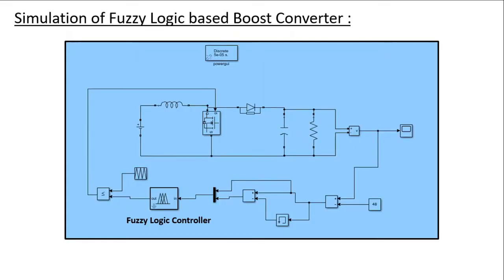This is a MATLAB model of a fuzzy logic based boost converter. If you carefully observe, we are using a fuzzy logic controller in the closed loop system. I made a couple of videos with respect to open loop simulation and design of a boost converter, and closed loop simulation of a boost converter using a PI controller. So over here I am using a fuzzy logic controller instead of a PI controller in order to establish a closed